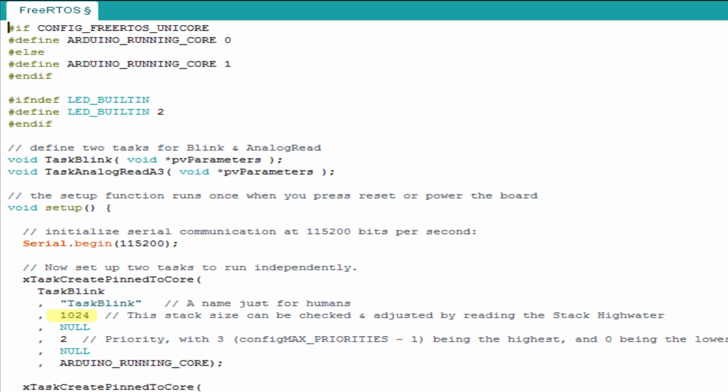Setting the stack too small can cause a stack overflow. A stack overflow is when data written to the stack exceeds the space dedicated to the data, and values are written over onto nearby memory, which may or may not contain other data. If these regions of overflow contain no data, there will be no indication this is occurring. But if this overflow region of memory contains important data, it will be overwritten and corrupted.